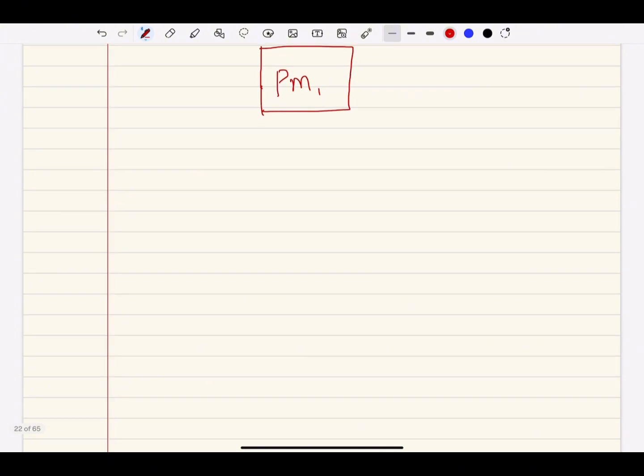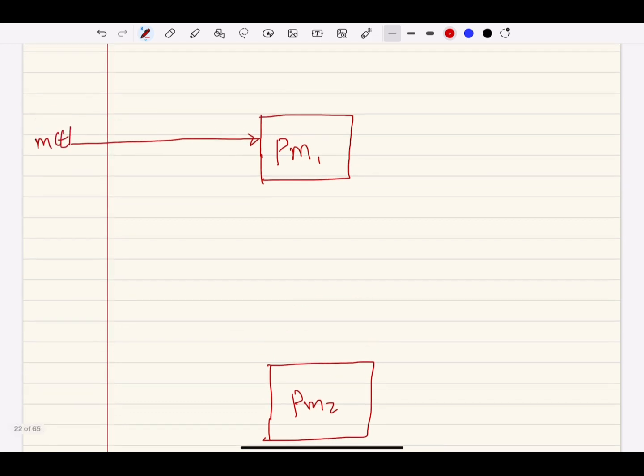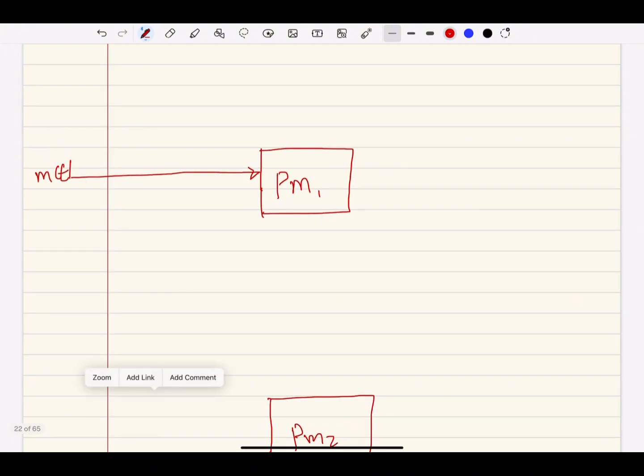So as I said, we need two modulators, which are product modulators, so PM1, and then we need another modulator, which is PM2. This is our message signal. It's going to this modulator, m(t). As the name suggests, phase shift. Remember that cos(θ − 90°) is equal to sin θ. And therefore, this is what we are going to refer to as our phase shift. So if it's being phase shifted by minus 90 degrees, we will have the resultant output to be sin θ.